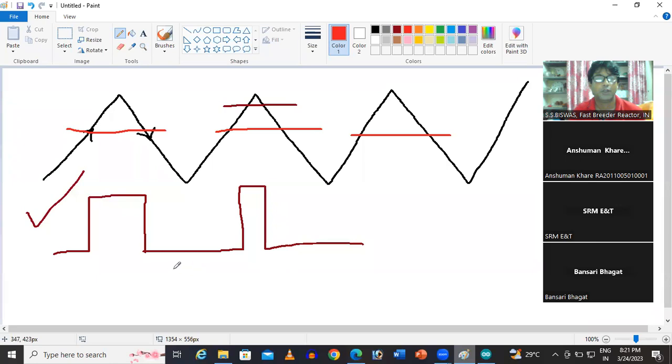Okay. So say earlier the pulse was high. So here it will be clear. And down counting, it will be set. So the down counting match will be here, so it will set. You see, you are getting the opposite kind of pulse, the inverted pulse. So this pulse is called inverted PWM.